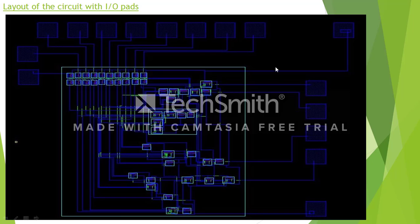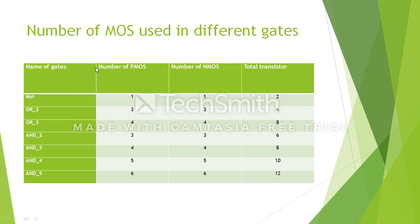In this diagram, we have used input output pads for the input pin, output pin, VDD and GND. Actually we have placed these input output pins in a random manner. We should place these input output pins in either bidirectional or quadridirectional fashion to design the medium scale chip. As a result, our total area has been increased.